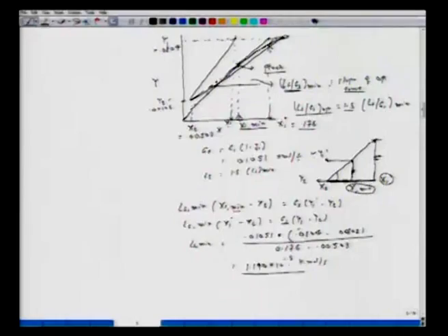Okay. We have the equilibrium curve which is given to us. We know the operating curve. Wherever there is a pinch, y will be equal to x, and that point will satisfy both the operating curve and the equilibrium curve. So one can obtain x1 min from there also. From that, then go back and put back the equations to obtain LS min. But if you have a graph and you do a nice job, then there is no need to solve analytically. So now we know LS min.